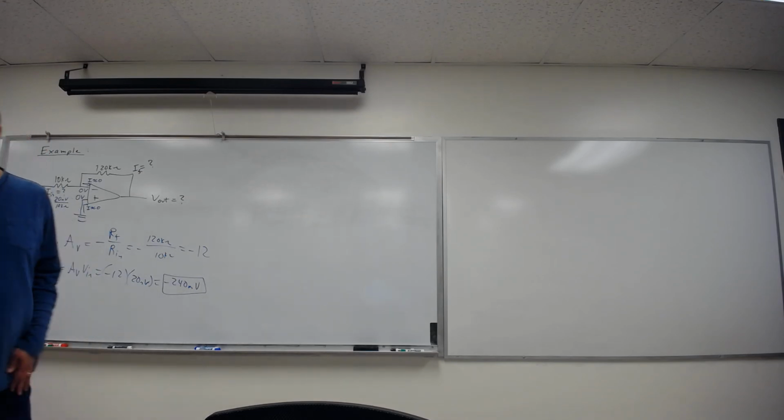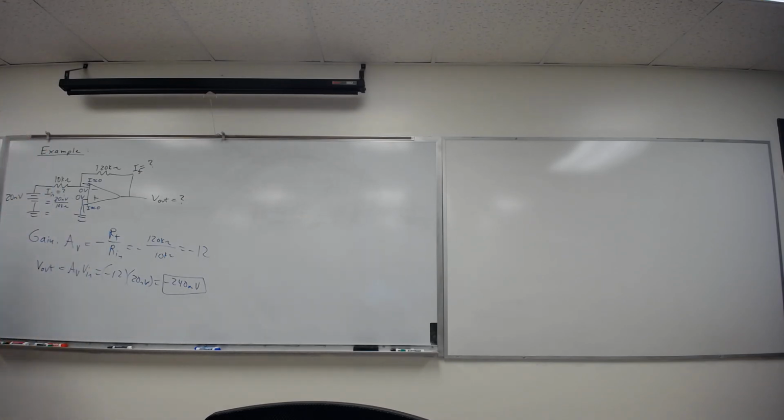What's 20 millivolts over 10? That seems like something I should be able to do in my head, but I'll mess a decimal point up. So 0.02 volts divided by 10,000 ohms is, I mean right there, 2 times 10 to the minus 6 amps. So my input current is down in the microamps.